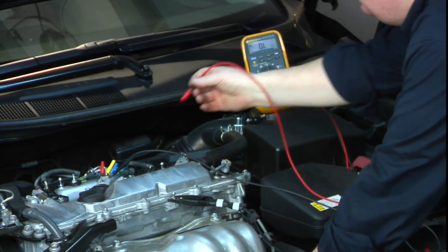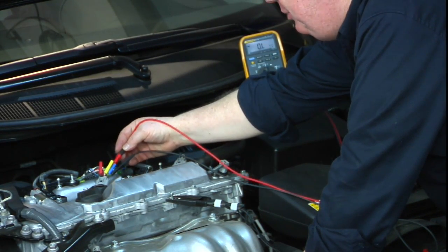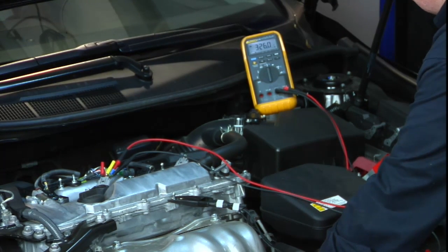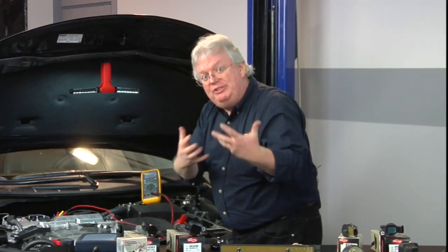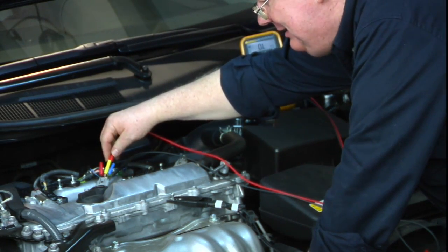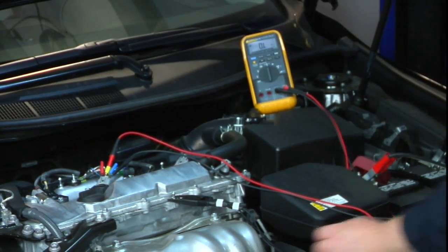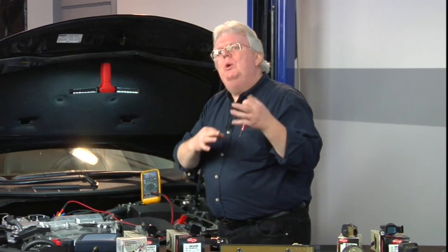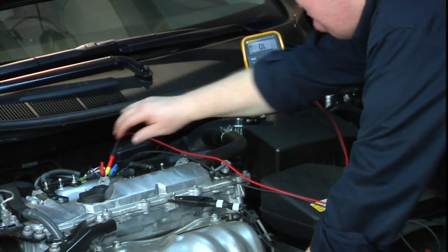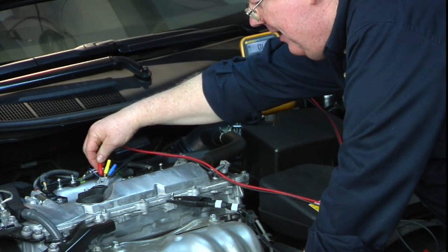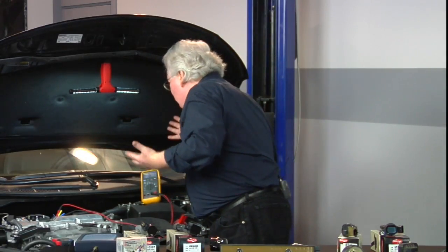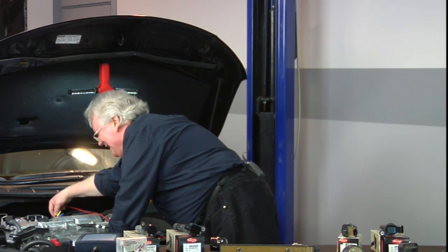All right. So here's our trigger input. Measuring between it and ground, we've got about 326 ohms. We have some kind of circuit there. It's not an open. Nothing really is going to tell us a lot here, because we're not going to be able to measure this coil like we would a normal coil, because it's a smart Coil-On-Plug 4-wire setup. But now this should show us how much resistance is in the entire circuit, and that's over limits. And there actually could be a diode in there.